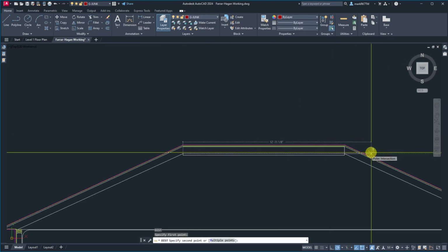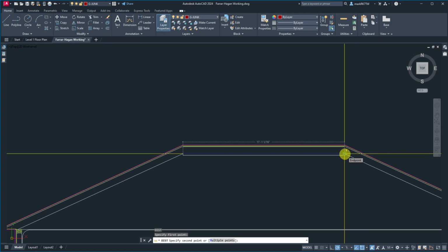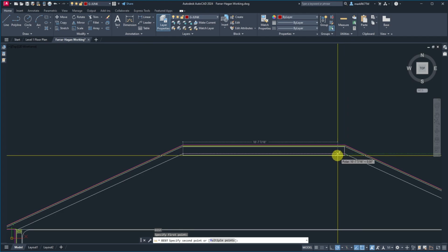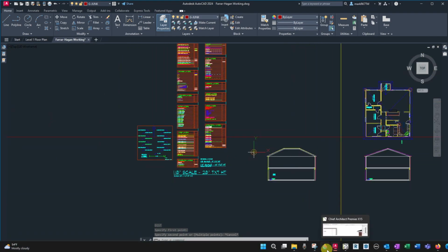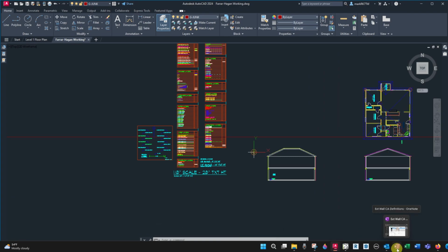So our distance that we measure here is 11 feet 1 and a 16th. So that's 12 times 11, and then another inch. That's kind of an oddity, but 12 times 11 is 132. So if I take that and divide it by 16 on centers, it's 8 1/4 of those guys. And I did count them in the video, which there is a live video recorded in the attic in lesson 2 that you can listen to.